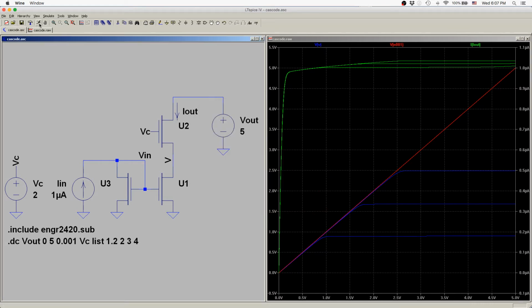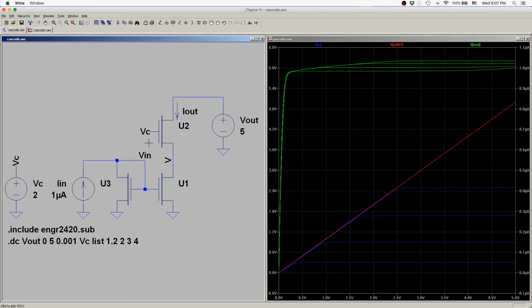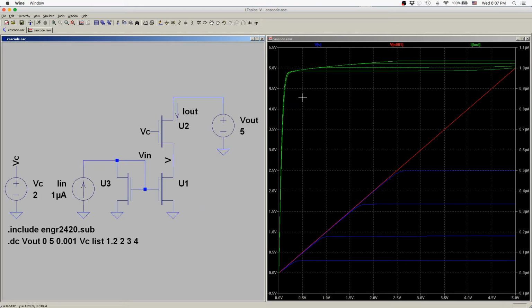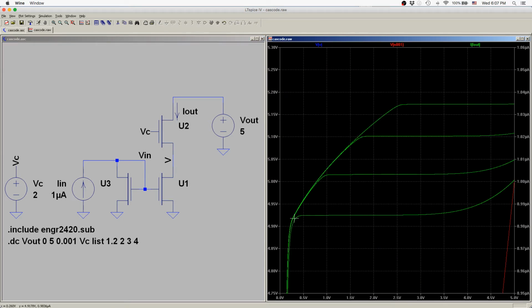and run that simulation, you kind of get to the point where, if you look at this, you can imagine that that region where the Cascode transistor is in the ohmic region and the transistor we're cascoding is in the saturation region is practically 0 at that point.